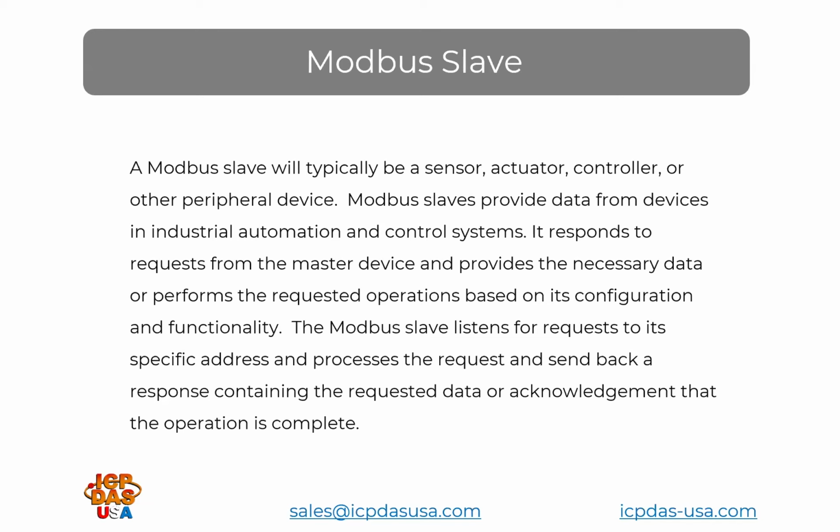A PLC connected to some temperature and humidity sensors is a perfect example of this. So let's say the PLC was tasked with monitoring a set of cold storage rooms. Each room will have a desired temperature and humidity requirement based on what is stored in the particular room. The PLC will monitor the temperature and humidity of the rooms with sensors and control the refrigeration to maintain the environment. It would also be able to monitor if the doors were left open or if the room were empty. It could either sound an alarm or adjust the temperature to save electricity.